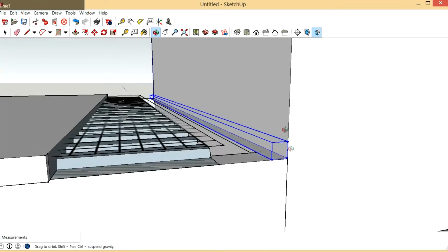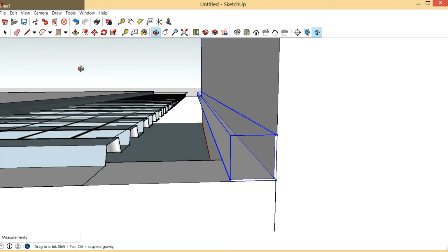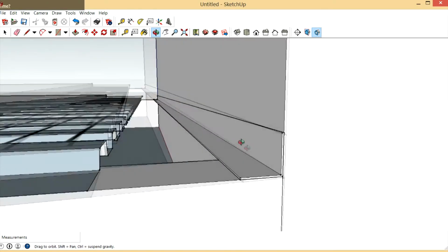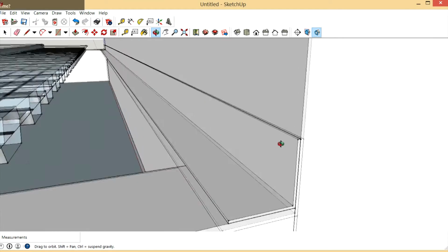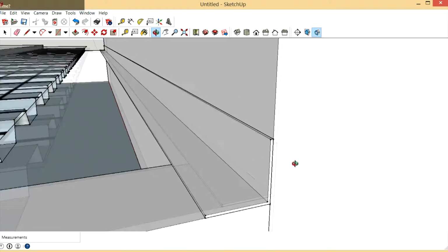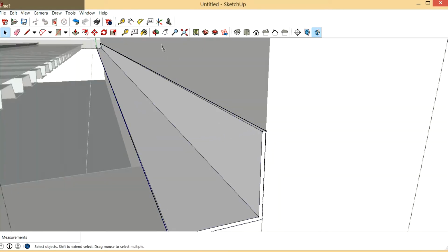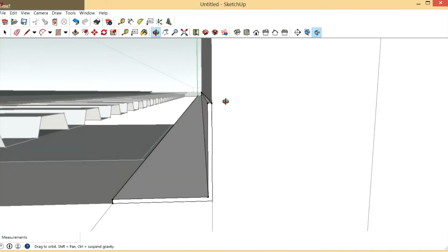So what that's going to do is force any water that comes down and gets on that out and over the foundation or gravel, whatever's down here. Okay, so now actually this flashing is going to need to be about, let's call it 10 inches tall. So what I need to do is edit this, and I just realized I'm under the slab, so I need to add that 4 inches. Gotta be careful here when I'm grabbing.